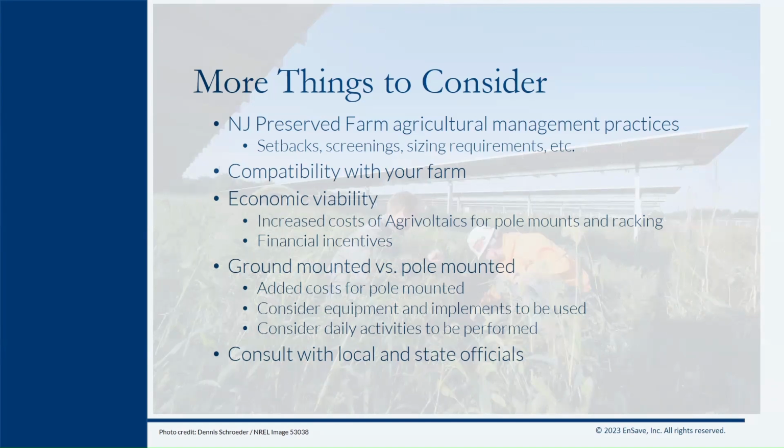You want to consider what equipment and implements are going to be used under that agrivoltaic system. And then, of course, daily activities. If you're going to be working underneath those panels every single day, if you put them flush to the ground and you're bumping your head every day, depending on what you're doing, that might not be ideal for you. You might want to raise them up just a little bit.